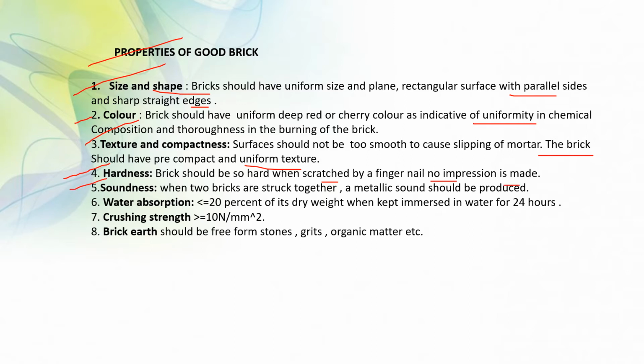When two bricks are struck together, a metallic sound should be produced. Next, water absorption is most important. Less than or equal to 20% of its dry weight when kept immersed in water for 24 hours. Next, crushing strength greater than or equal to 10 Newton per meter square. Next, brick earth should be free from stone, grit, organic matter, etc.